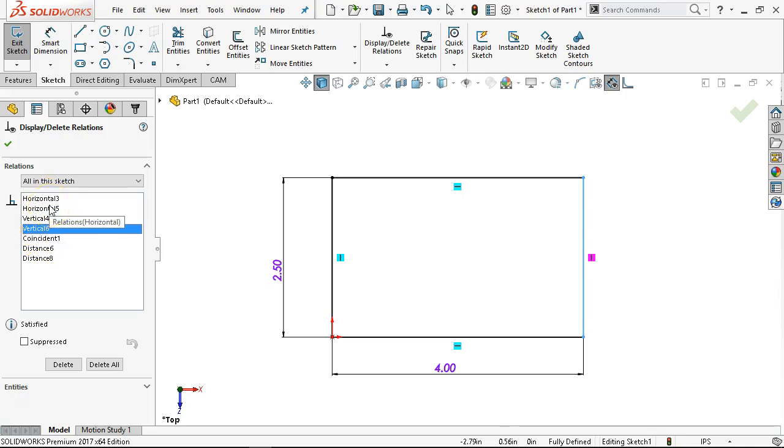If there is an underdefined, not solved condition, these will show up in amber, red, or yellow, and you can identify them. Unfortunately, the one that's showing up in amber, red, or yellow is usually under the first one that's blue, and unless you click something else, you won't really see it. So it's one of those, I know you're there somewhere. I can see over here that I'm having a problem with an overdefined, unsolvable condition. None of the relations are having a problem until you click and, oh hey, the very first one that was selected, highlighted in blue, was covering it up, thank you very much, and is now accessible.